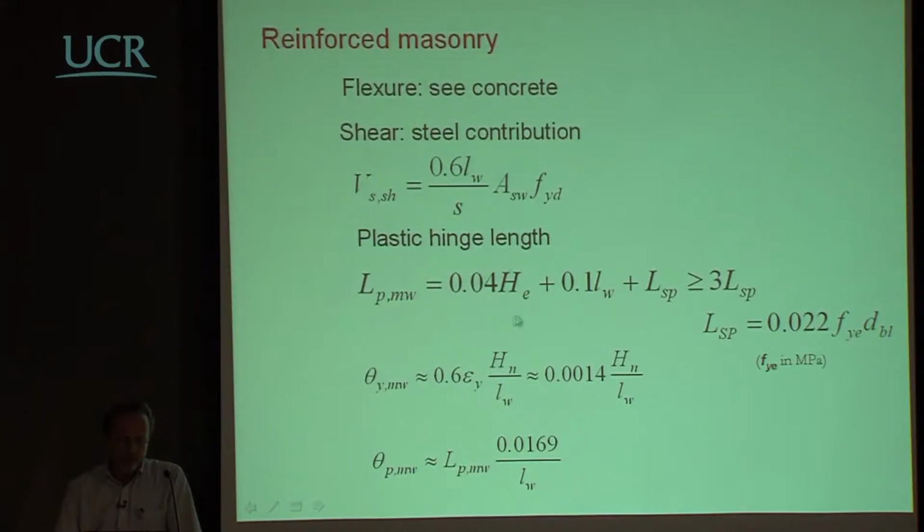This is different because, again, there is a different efficiency in the vertical direction due to the loss of bond. And of course, you can count on this part here that in many cases is giving the main contribution because again of the low bond efficiency of a masonry structure. So this factor of 3 is just because this factor is taken from the case of concrete.